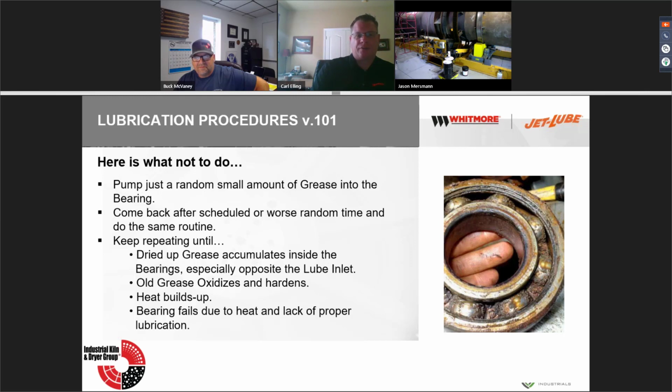Or you come back from a schedule, or worse, a random time, and you're doing the same kind of route and you're just randomly greasing. Pick a spot, find out where you stopped, and then start at the next one. Just be aware of what you're doing so you don't over grease. But if you keep repeating these things, you're going to end up with these particular situations. You get dried up grease that accumulates inside the bearings, especially on the opposite side of the lube inlet.